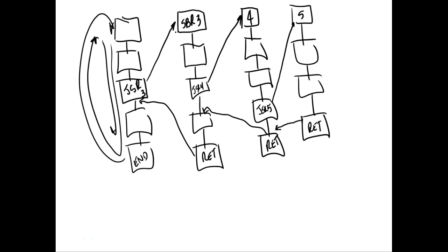Now later on, when we look at this, we have the ability to change the stack. Normally we don't do that. But if I know where the stack's at, what can I do? Now we can change it. Yeah, we could adjust the stack pointer. It's nothing but memory. It's read-write memory, which means what? It means you can change it. So we could change the return. We could make a program that changes the return address if we wanted to. But right now we're not doing it. It's something we don't do. In microprocessors, we have an application where we deliberately went in there.